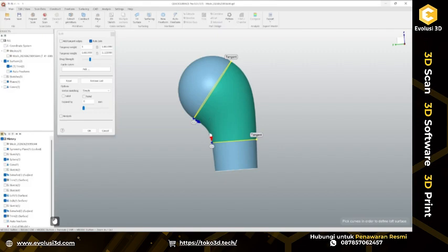We can get really close, but not perfectly the same as it was designed. This is one thing. Another thing is, every CAD package uses slightly different settings for everything. So you can create absolutely the same features and then create a loft between them with the same tangency weights, and the result will be just a tiny bit different in each CAD package.